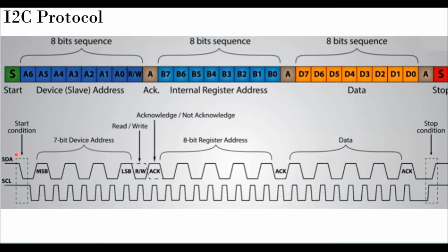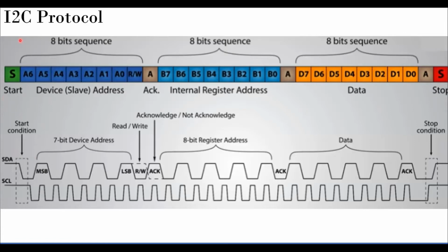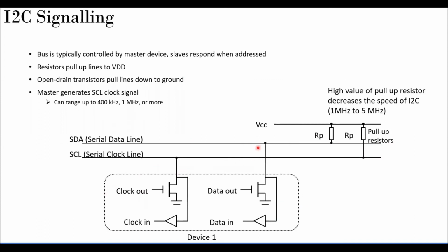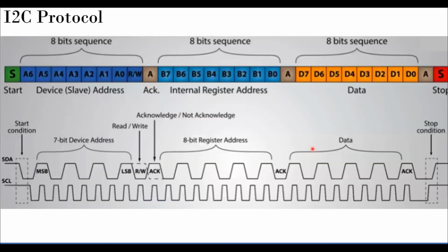And remember, as I said, in this case it is always put as high. So the idle state is always high. If you see here SDA, the normal state is always high, and the operation is done, and again it goes back to the high state. So that's the key aspect. Okay, so start is always issuing a high to low signal. Similarly, the clock also is similar. I'm sorry to go back again and mislead you. So both are actually tied up to the high state. You can see over here. The same scenario is there for the UART also. Okay, so this is the way it goes.